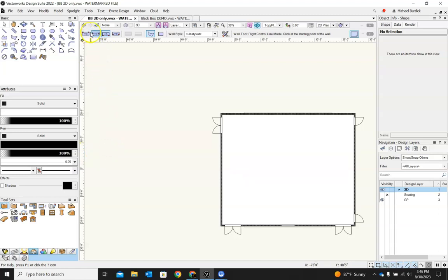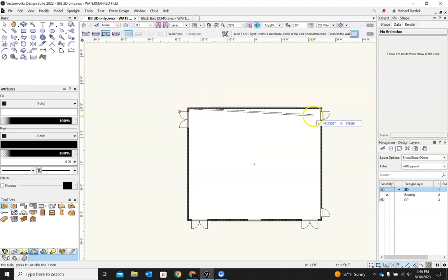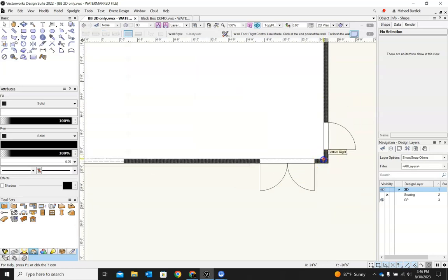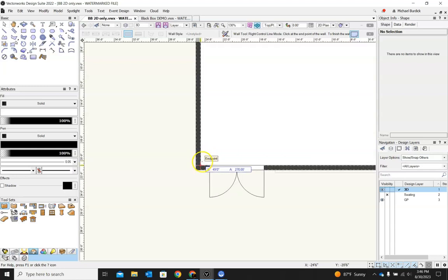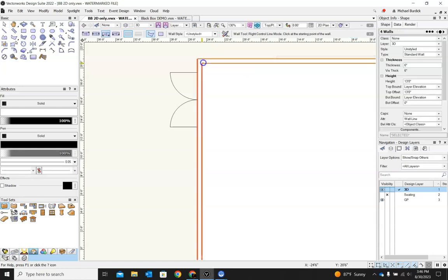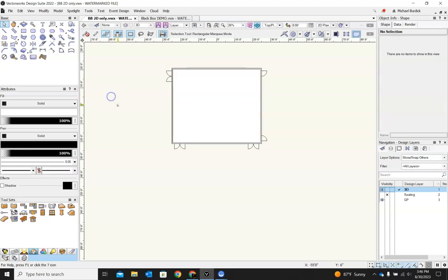It's very similar the way you lay this in to our double line tool. You can choose which corner you're going to be clicking on and which side it will follow you on. So we'll click this one. Then I'll just start here on this corner. Because I have Show Snap on, it's snapping right to our 2D ground plan. It'll come down to this one, and this one, and then I'll just close that off. Right there. And that has drawn our 4 walls.